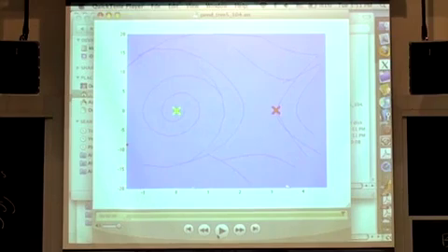Because we can suddenly, for the LQR controller, right? It depended on the thing we've worked out: if the cost-to-go function is this, or in the time-varying case this, then I can come up with a very nice representation of the basin of attraction based on just a scalar value. And I could just start designing funnels through my state space, right? And the vision is, if you can think about the funnels as you build them, then you don't have to build too many trajectories to start filling the state space.